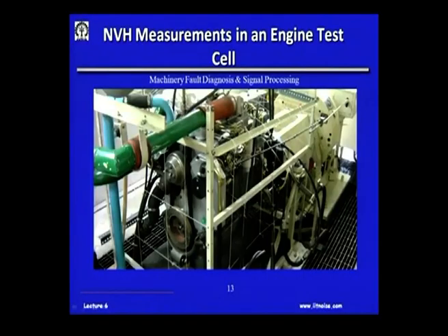In closing, this is one last slide wherein you will see the tuned dynamic torsional damper here on this engine. And if you will recall, here in this engine we had done a lot of unconstrained layer damping to the oil sump to reduce the radiated vibration and noise levels. This is actually in an engine manufacturer's test cell where we are doing some vibration studies on the engine, and particularly this is the torsional damper, because there is a crankshaft here and this is a 6-cylinder truck engine. So, these oscillations are reduced by having this torsional damper over here.